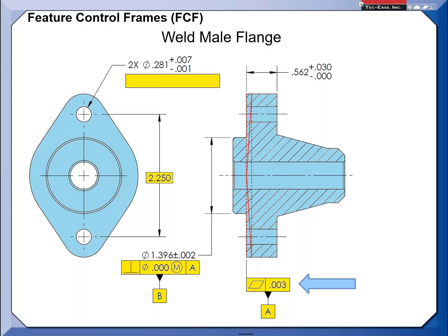So dealing with the flatness control, these are some elements that engineering would have to consider. Right now, I just threw a flatness on it, but there are things engineering could have done to minimize this. Now, I personally have experienced this. I had a vacuum chamber. My vacuum chamber door was 4 foot in diameter, and I had an O-ring compression seal.